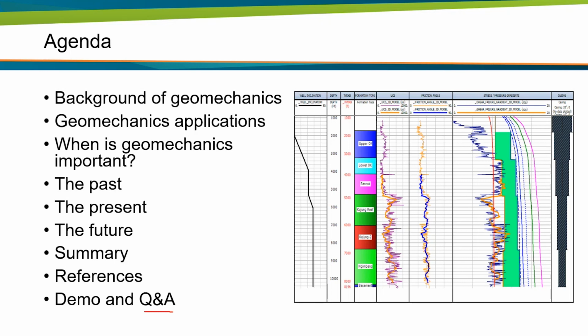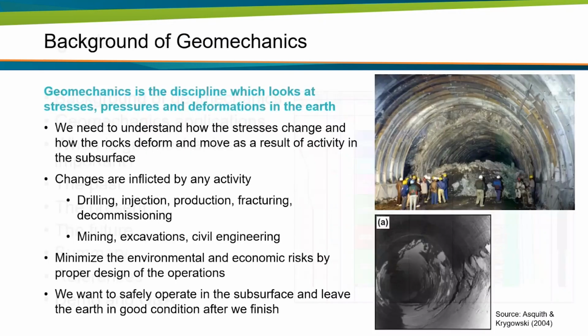Okay, so let's go to the background of geomechanics. What exactly is geomechanics? Well, that's the discipline which looks at stresses and pressures in the subsurface and changes in those stresses and pressures. And when stresses change, the rock reacts to that. The rock deforms, and the rock can deform elastically, or it can actually break.